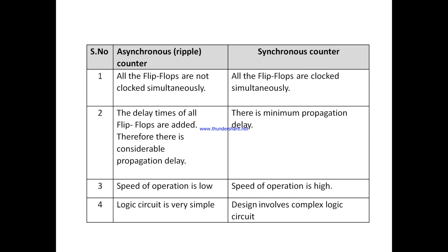This is the basic difference between synchronous and asynchronous counters. In an asynchronous counter, the flip-flops are not clocked simultaneously, but in a synchronous counter all the flip-flops are clocked simultaneously.